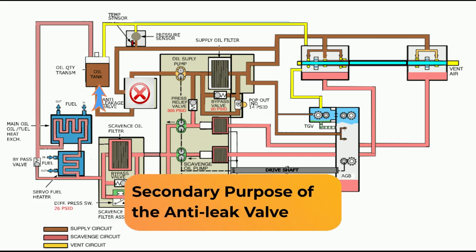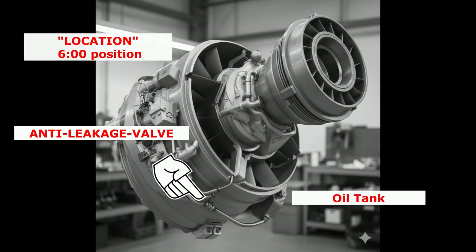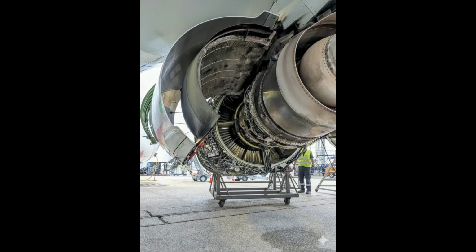Secondary purpose. The second objective of the anti-leak valve is to prevent the oil in the reservoir from draining out during the removal or maintenance of any lubrication system component. Location and access. The anti-leak valve is located on the fan case at the 6 o'clock position. It is installed on the oil supply line leading from the oil tank to the lubrication unit. To access the anti-leak valve, the fan cowlings must be opened.